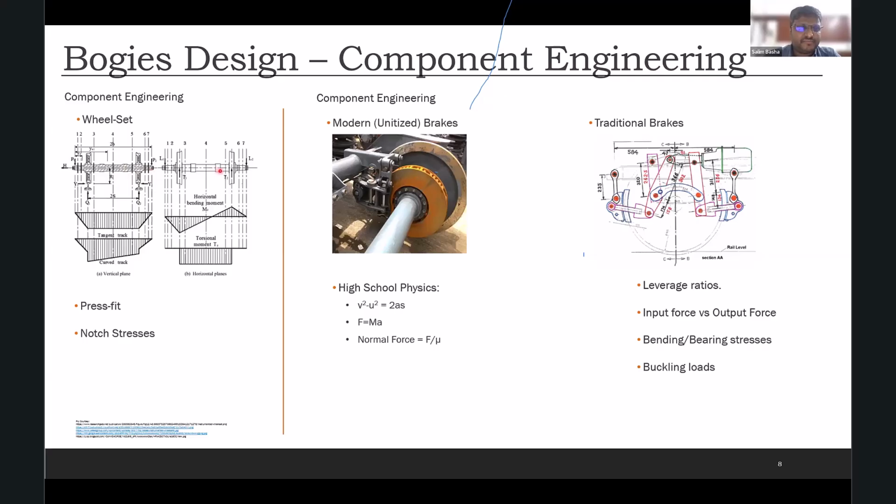And then we have the tractive effort and the braking loads as well, which will get applied in a different plane, and they generate a different set of loadings. So we need to combine all these and then ensure that the axle has been sized to take up all these loads. So this is about the wheel set.